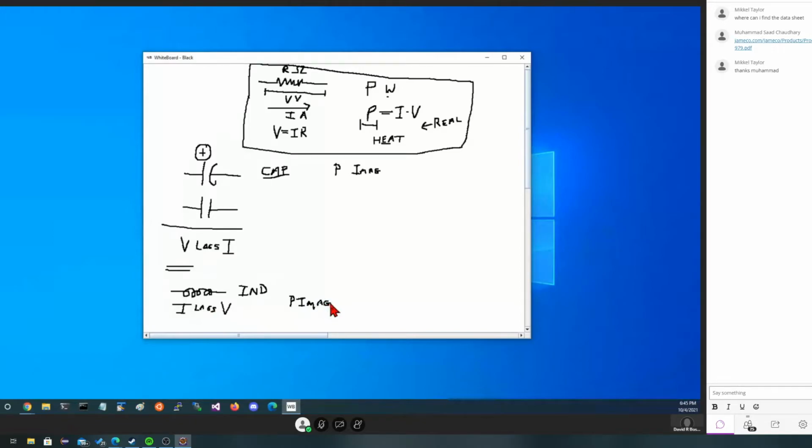We won't talk about them too much after tonight, but if we ever do anything with a motor, or we have anything like a solenoid that has a coil, or if we were building a receiver for an antenna where we have to balance the amount of capacitance and inductance in a circuit. These don't really have what we would call a resistance. Instead of a resistance, we're going to use the word reactance. So a capacitor has reactance. An inductor has reactance. And they're the imaginary versions of resistance.